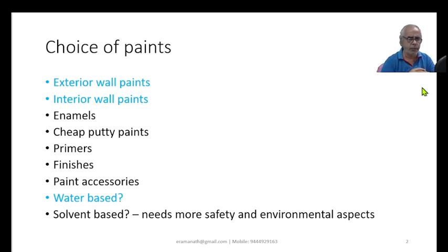I have listed a few here: exterior wall paints, interior wall paints, enamels. Enamels means dry, air-drying enamels in this case, because we have got stoving enamels also. And then we should be aware of the cheap putty paints. So these paints are applied after the primer.